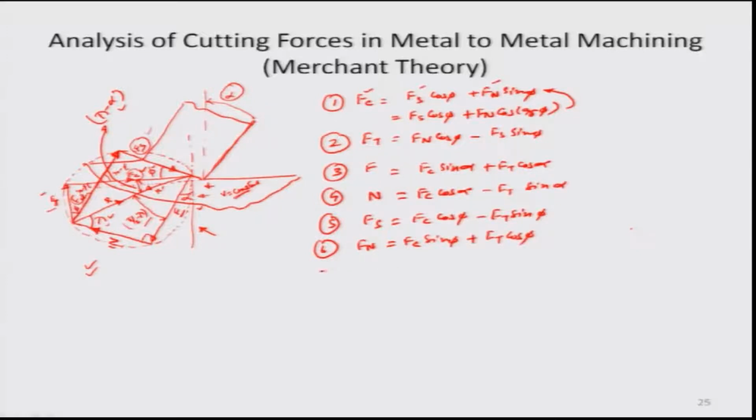The resultant reaction R can be recorded as Fs divided by cos of phi plus lambda minus alpha. If you can see here, this right here is lambda minus alpha, and you have an angle phi here plus lambda minus alpha as this total angle, and what you are doing is essentially you are resolving the R cos of phi plus lambda minus alpha, R being this particular vector. So, you are resolving this vector in this direction, the Fs direction, and that is the Fs. Okay. So, here is where you have a relationship between R and Fs.